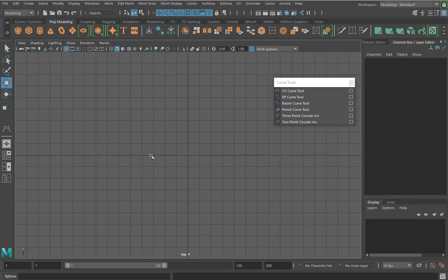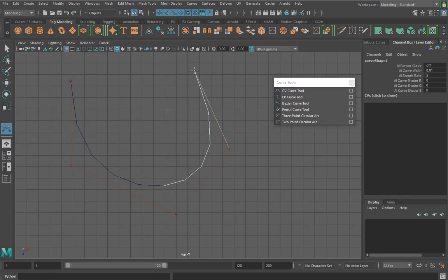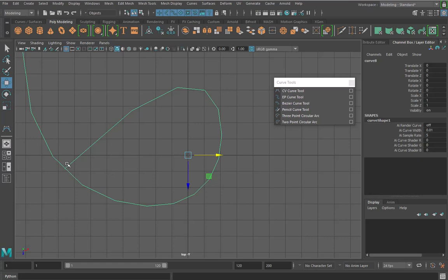There is another key which is C. We use a shortcut key, sorry, and V. I'll just go through them again. This time I just click drag on the grid, third, fourth, and then I hold the C key. And with the C key, as you see, the vertex is moving on the line, or on the curve. So when I let go and press enter, see, it just touches the line.